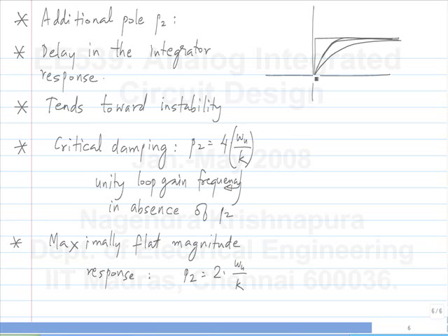But if you try to increase the quality factor beyond this, it will do something like this. And depending on what your settling accuracy is, this may be acceptable. So what is an acceptable amount of ringing very much depends on the application. Maybe depending on the error value, a little bit of overshooting and coming down is acceptable. But certainly, when you make an amplifier, something like this would not be a good thing.